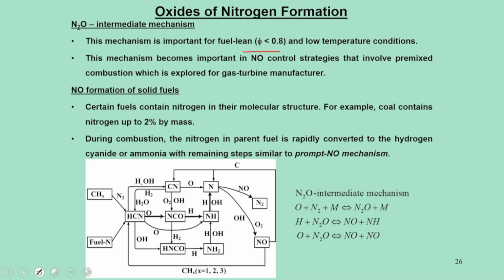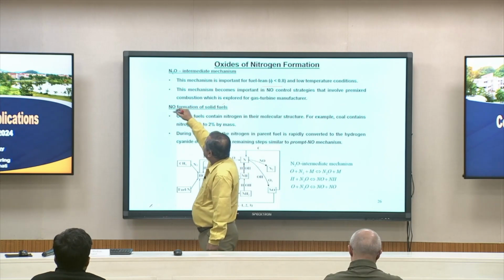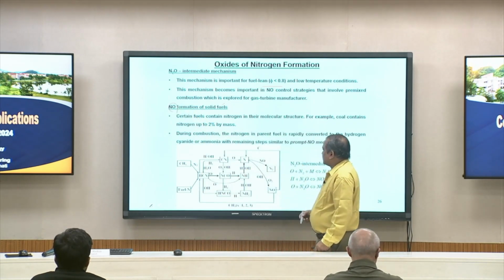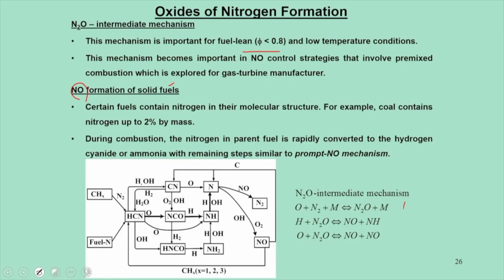It is seen in the gas turbine environment. This is also similar to the NO effect as we saw in our previous case. And there are some possibilities that when we are using solid fuels like wood burning, we can have NO formations. So, solid fuel NO formation is governed by this. This is initiated through this N2O intermediate mechanism.